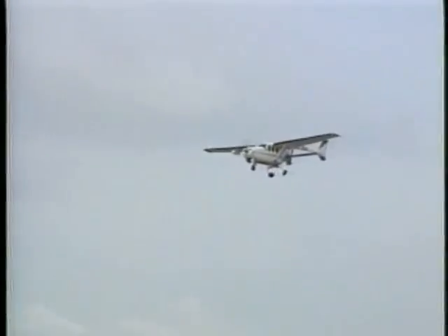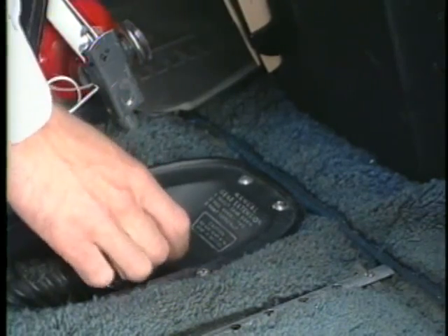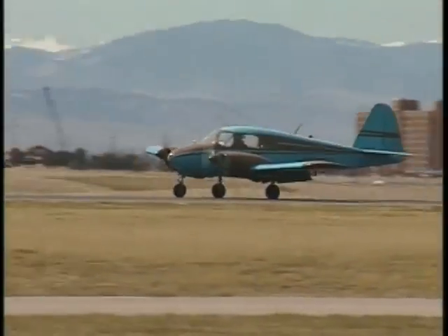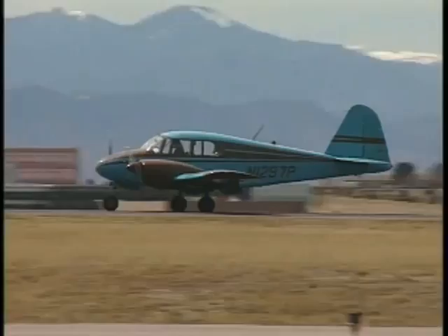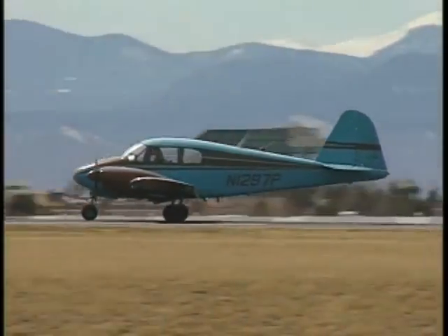This system also has an emergency feature should an engine or hydraulic pump fail. Backup hydraulic pressure can be supplied by an electrically driven hydraulic pump, or in the case of some small general aviation aircraft, by a hand pump. In the unlikely event of a hydraulic leak or loss of hydraulic fluid, some aircraft have tanks of compressed air that may be used to blow the gear into the down and locked position.